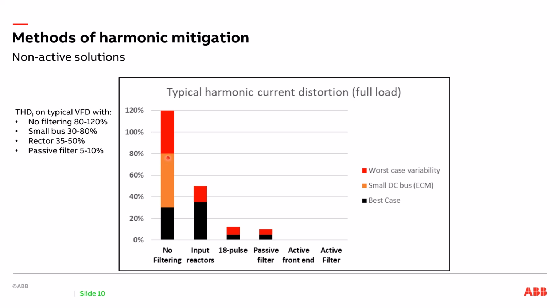And you can see lower current distortion numbers, but as a negative, it really impacts your voltage distortion. So it's not something I'd recommend. You see it in certain VFD designs, and also some of the more modern ECM designs are trying to play that trick. The next step you typically do is put in an AC line reactor in the drive, or a DC bus choke from a harmonic mitigation standpoint, doesn't matter.